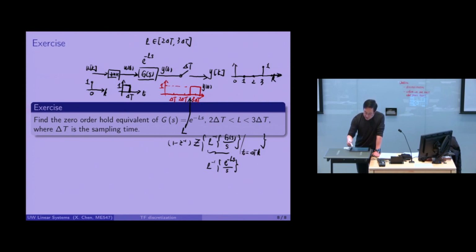If you take a look here now, the input is an impulse. The output is an impulse delayed by 3 steps. Then you can see that the transfer function is nothing but z to the power of -3. It just delays the signal by 3 steps, right?